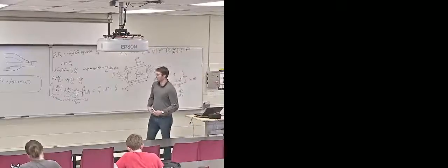Now, this may seem redundant, but we'll go ahead and multiply this rho back through one more time now that we've made the assumption. I'm going to write it over. Here we end up with 1/2 rho v squared plus rho gz plus p is equal to a constant. And this, ladies and gentlemen, is the Bernoulli equation. This is the much celebrated, much used, much abused, loved, hated, in all forms, Bernoulli equation.